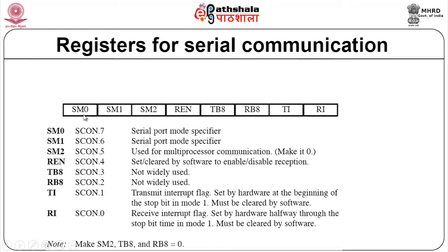These two things are very important to set the mode, and REN is very important to set whether we will be enabling data reception. If I set it to one, then it is enabled for reception of serial data. TI and RI are the bits which will be set by the hardware.